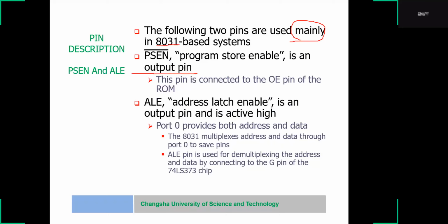This pin is connected to the OE pin of the ROM. ALE, address latch enable, is an output pin and is active high.